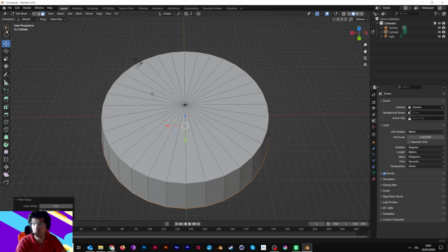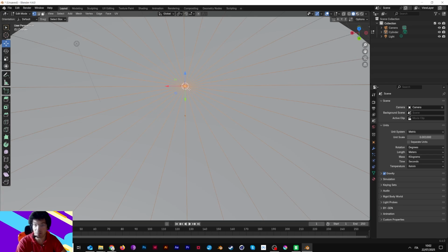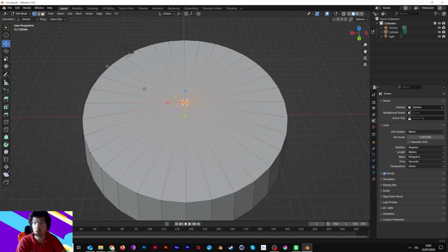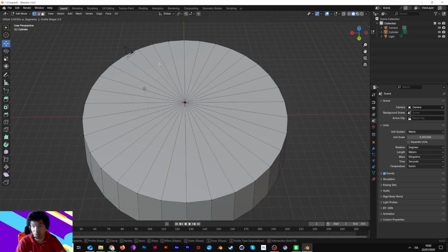Now you can select the vertex mode, and you have to select the vertex right there. It's invisible right now, but we need to create something bigger to have more geometry. So you have to press Ctrl B to enter in bevel mode.